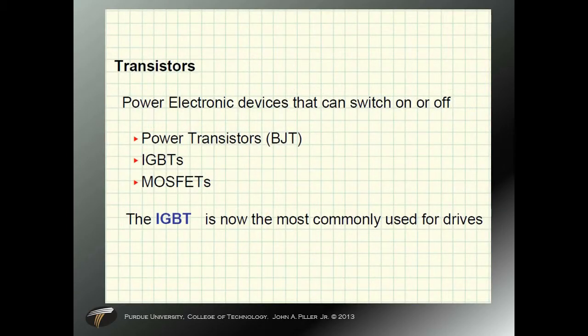Transistors will be required to adjust an output waveform. Transistors can be used as silicon relays. Via a pulse width modulation circuit, we can adjust the output waveform and even create a sine wave-like signal or a sine approximation. BJTs, IGBTs, and MOSFETs are all similar devices. Generally speaking, right now, IGBTs are the common device used in the power industry.